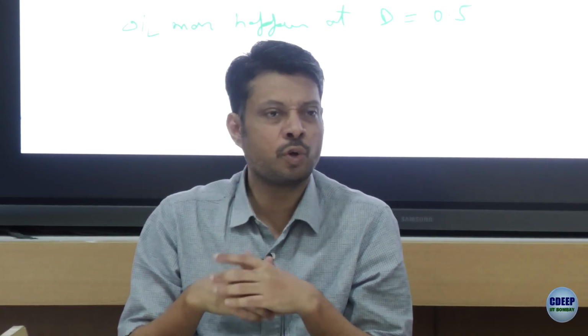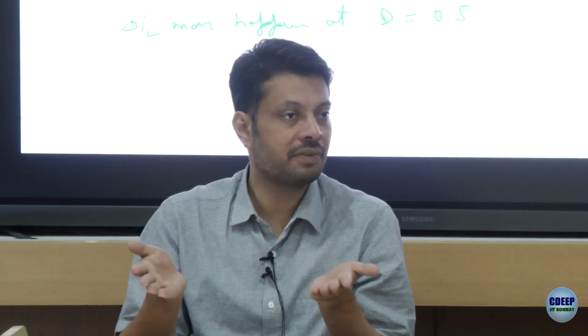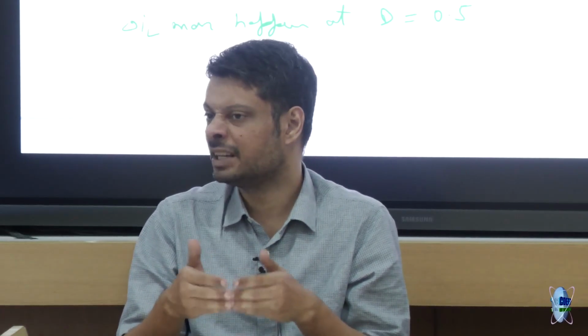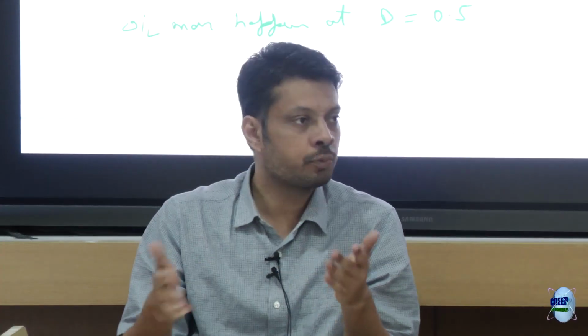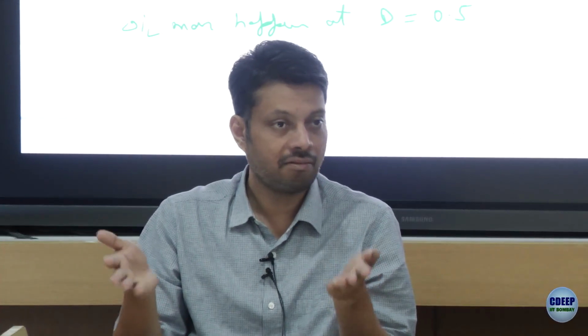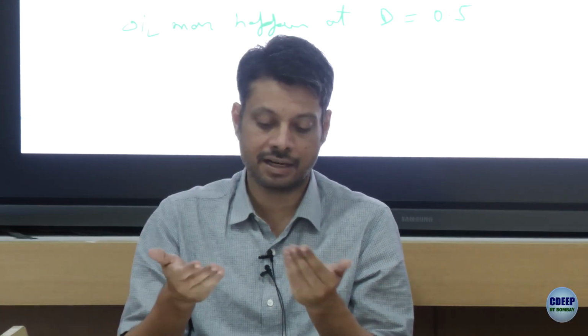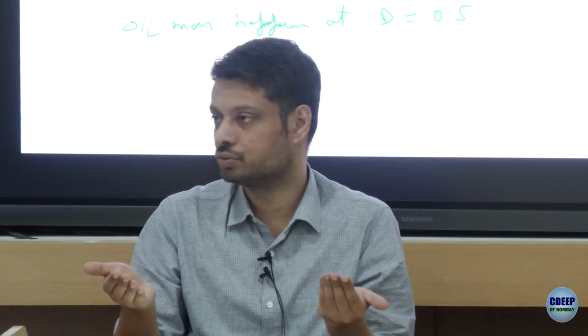Usually you won't be able to adjust duty cycle, right? Because your input is, let's say, 48, your output is 12. So your duty is already fixed. So although yes, it's good to see what is the trend with duty cycle, but it may not directly help you if the input and output voltages are fixed, right? D is already fixed. What you can choose is switching frequency and inductance. These are the only two things you can choose.